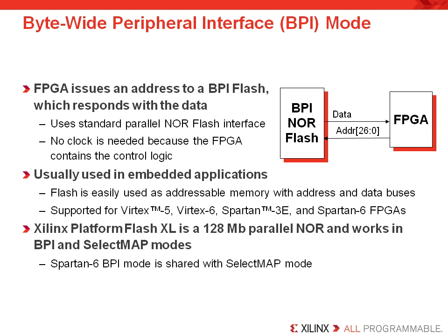The BPI interface also functions with Xilinx Parallel Platform Flash PROMs, which includes a 128 megabit device. There are a number of NOR flash memories that are currently supported, including Numonyx and Spansion. But be sure that you check the configuration user guide for your FPGA's uncompressed bitstream size. This will help you determine which NOR flash PROM is big enough for your bitstream and, if necessary, your design software code.